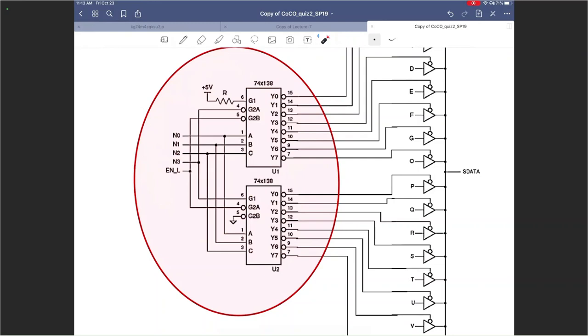Well, in general, there are no limits to cascading, because each of them individually is being powered by a 5-volt source and a ground supply. So if individually they're all getting their power, then there is no fan-in and fan-out limit I need to worry about, because voltage-wise, they're all going to be okay.